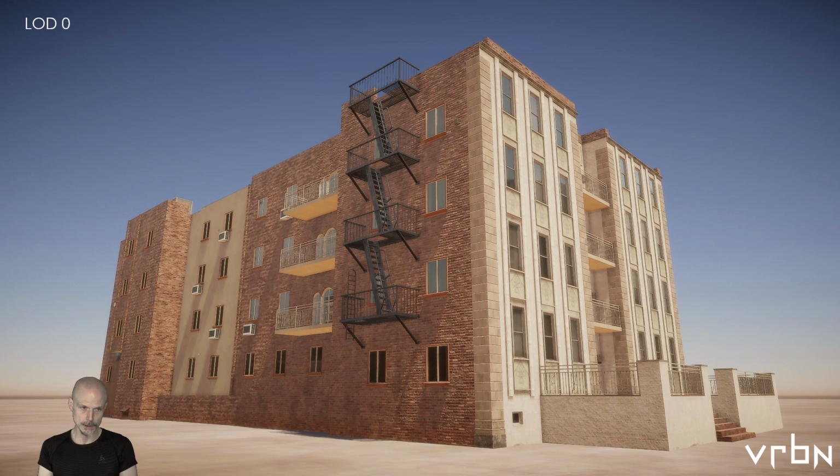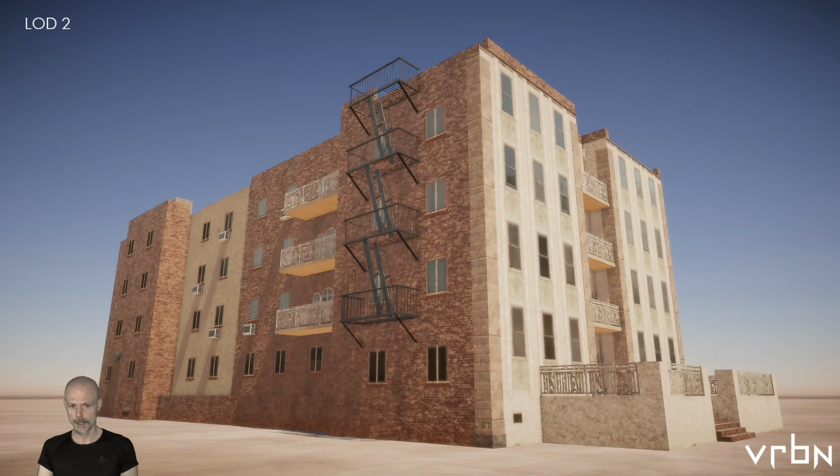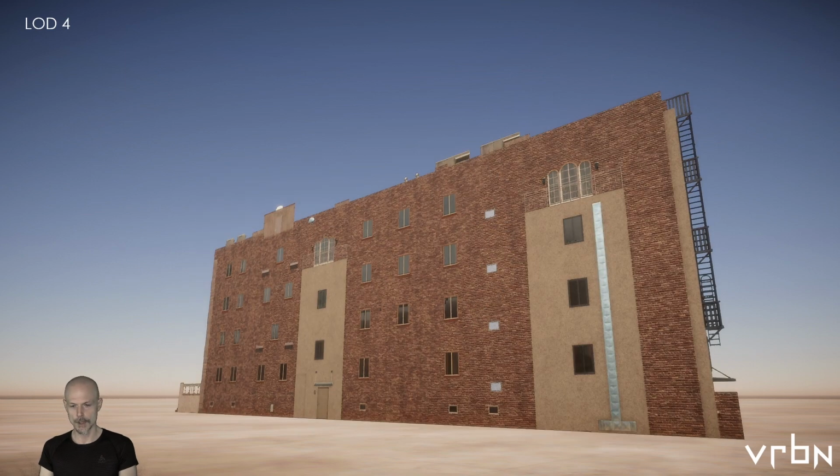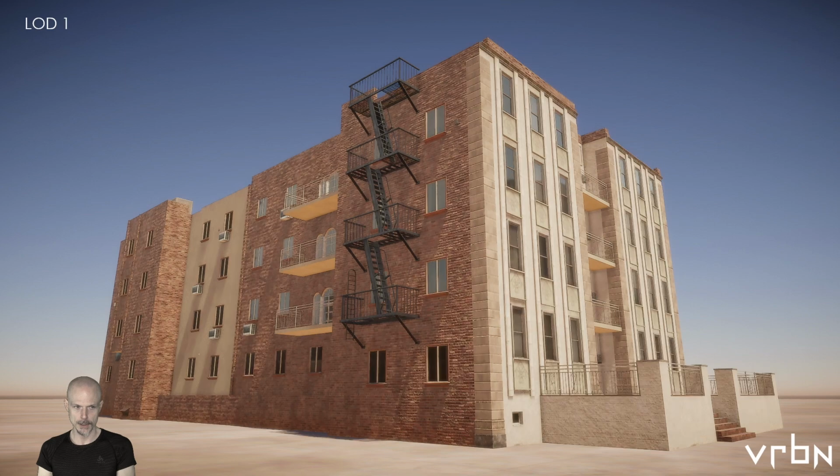So let's cycle between the LODs. So LOD 0, highest. LOD 1 actually has about 50% of what we just saw before. So I'm going to toggle. Let's go back to LOD 0, 1, 0, 1. Again, about the 50% reduction. Then going on to LOD 2 is a lot less polygons. Again, and then LOD 3, that's very common, the imposter, and then LOD 4 for very, very far distance cards that are typically orienting themselves towards the camera. Let's step again through it.